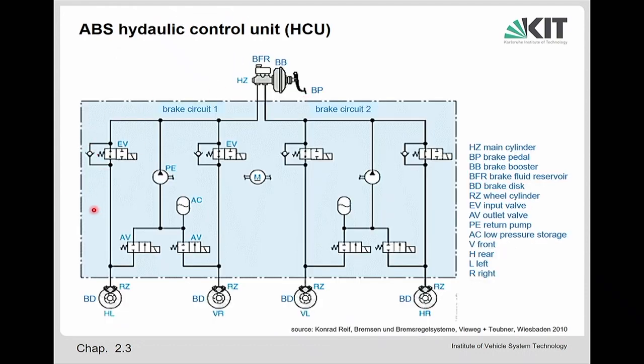This one? You are talking about a normal braking or an ABS braking? ABS braking. Yes, this is not a one-way valve. No. This one? This one is a one-way valve. Yes. Fluid can only go from the wheel brake back to the reservoir. This one is closed.